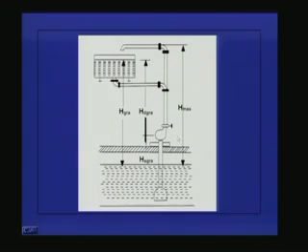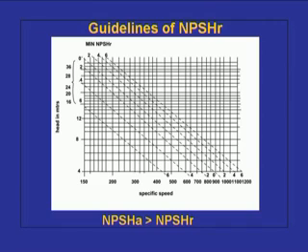If the pressure here, the below atmospheric pressure here itself, is very low, then one can expect more significant below atmospheric pressure within the pump. So, each pump manufacturer tells you what we call the NPSH required, that is net positive suction head required at the suction side.